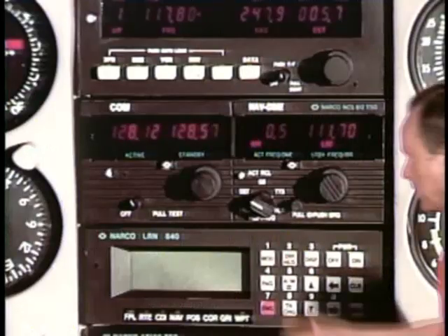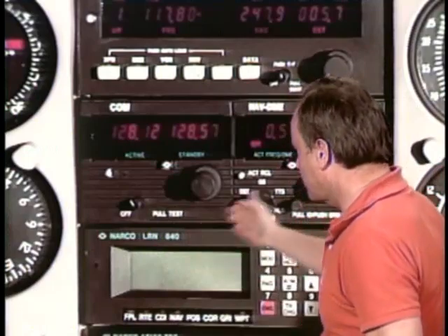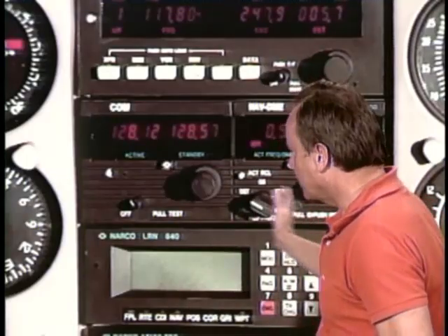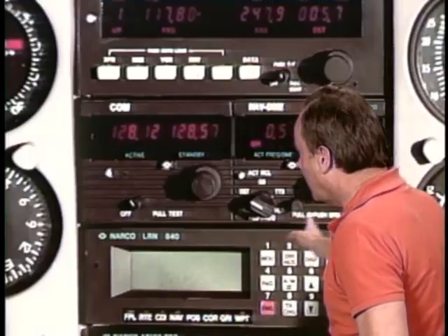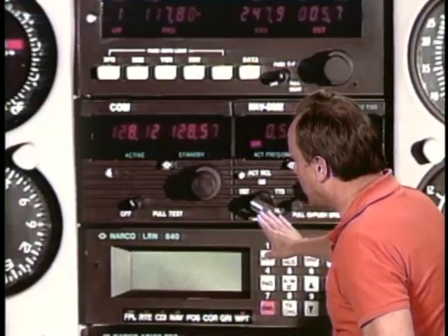Now let's assume as a mechanic you install radios or avionics in an aircraft and the associated antenna systems associated with those avionics, and let's assume you install them forward of the CG limit. Now the question is, is this going to affect the empty weight and the useful load of the aircraft? And the answer is yes. Anytime you install some new equipment in an aircraft, including avionics and antennas, it does affect the empty weight and useful load of the aircraft, and you would have to recompute the weight and balance of the aircraft.